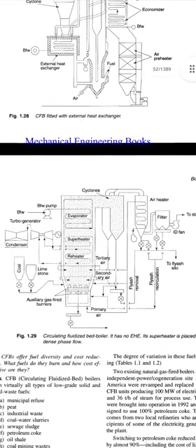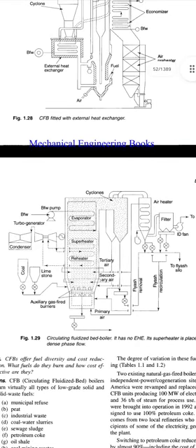In the water circuit, we can see the boiler feed water pump on the left side of the boiler, at the top of the boiler, and the feed water pump is pumping the water to the evaporator, then it goes to the water wall panels, then to the superheater, reheater, superheater. After that the superheater steam goes to the turbine.